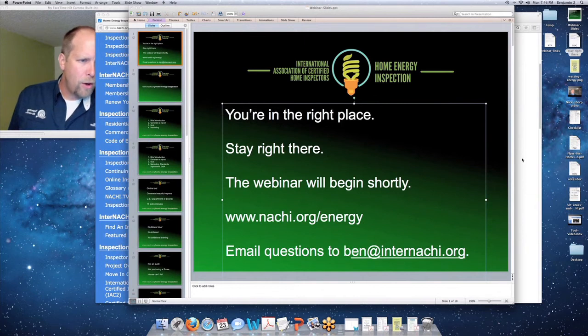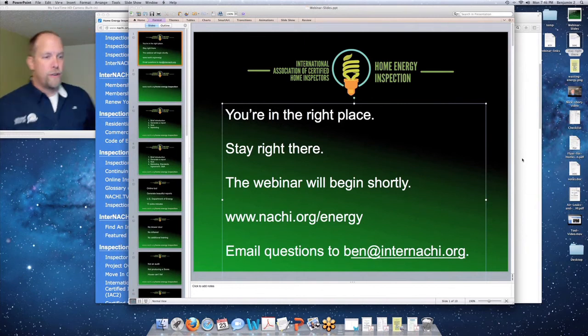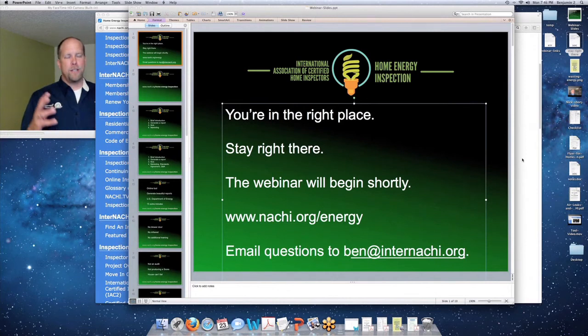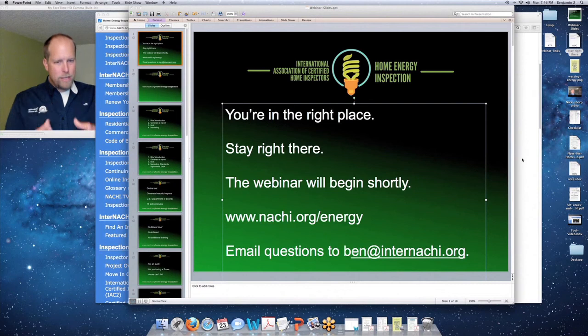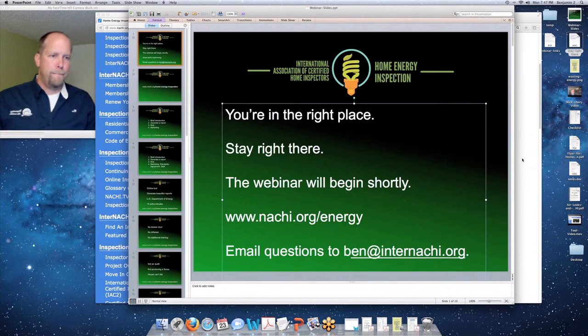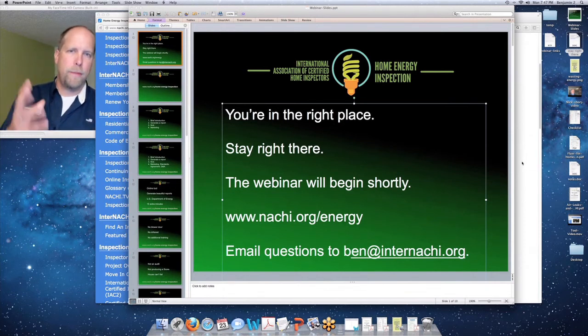program. What if there are 2 AC units, 2 furnaces, 2 water heaters? It's very easy. You add them up. So you add up the BTUs. It gets a little tricky with the years, right? Because maybe one is replaced and one is not. So remember, this is for the general average typical American home. And the average typical American home doesn't have 2 or 3 heating systems or cooling systems. If it does, then there's a little help menu. You go into the tool and it tells you to add up the BTUs. That's what we really want. How many BTUs per square foot? How much energy is being used in the square footage?